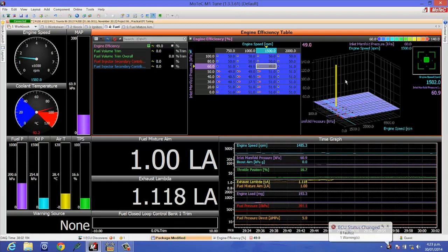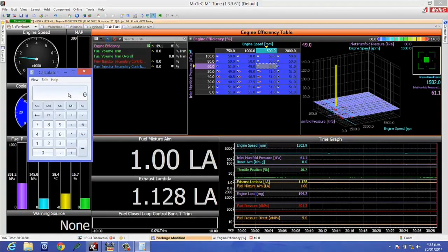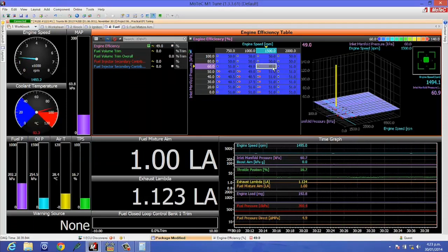What we want to do is check the measured air-fuel ratio and compare that with what we want. If there's a difference, then we can correct this using the have over want formula we learnt in the EFI fundamentals course. Just take the measured air-fuel ratio, or the air-fuel ratio we have, divide it by the target air-fuel ratio, or the air-fuel ratio we want, and you'll end up with a correction factor. If you apply this to the number in the current cell, you'll end up with the right lambda value.